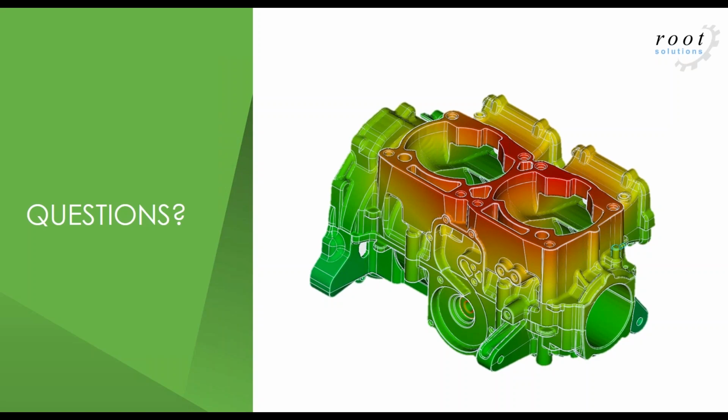There was another analysis that we did on a V8 model. I think the accuracy was within 5 or 6% compared to Creo Simulate, so pretty close. But the solution that we got in Creo Simulate Live was done in 10 seconds, where it was a 3-hour process for Creo Simulate. So the idea is that we give you powerful capability that is very simple to use and gives you results far quicker than a traditional simulation process. Getting that instant feedback means it's much more of a reality to bring this into the design environment, the design process.